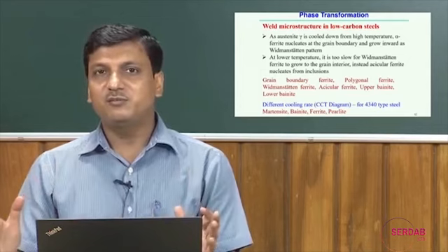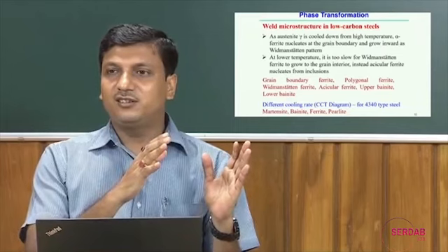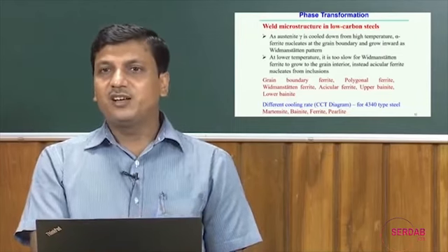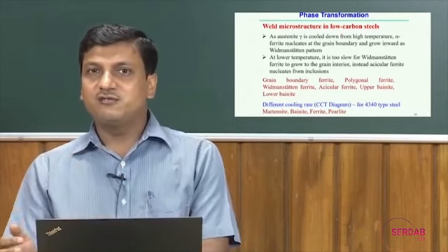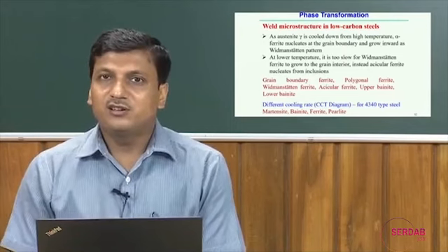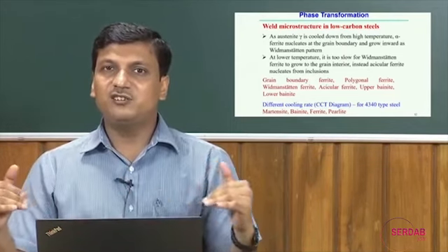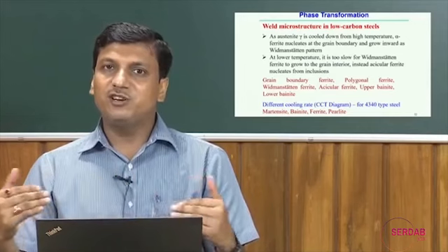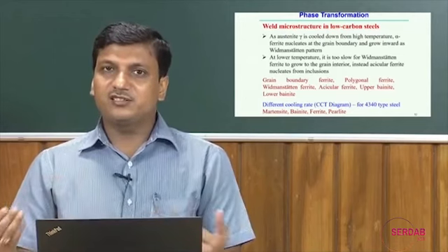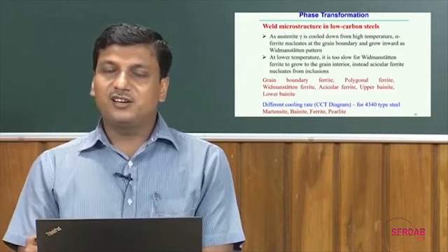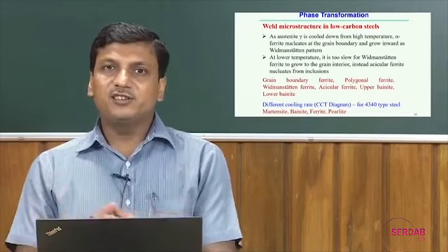That is why it is very important during the welding process to estimate the cooling rate, since in most cases we can find a link between the rate of cooling and the typical microstructure, and finally that microstructure decides the mechanical properties of the weld joint. But the link between all these three components is not very straightforward, and may not always be linear. There always exists a non-linear relationship, and that relationship varies depending on changes in the alloying elements.